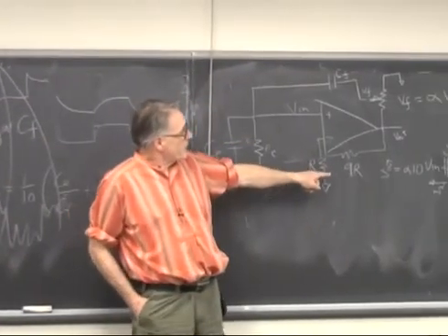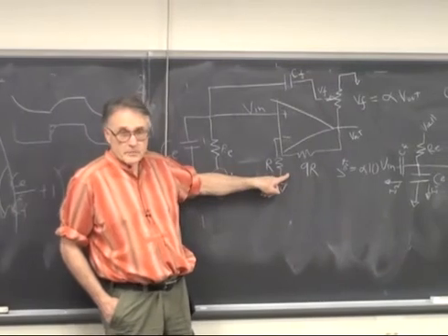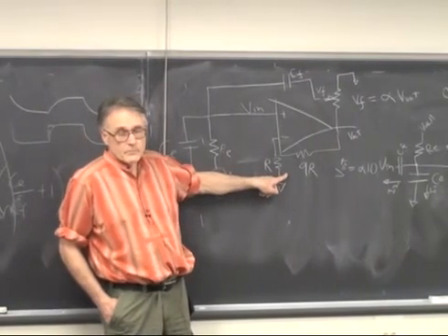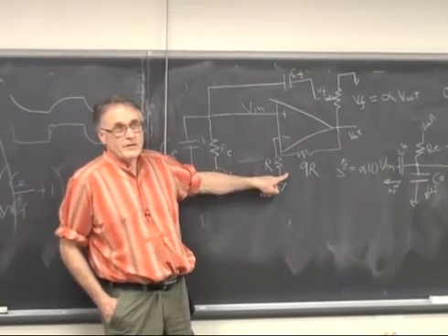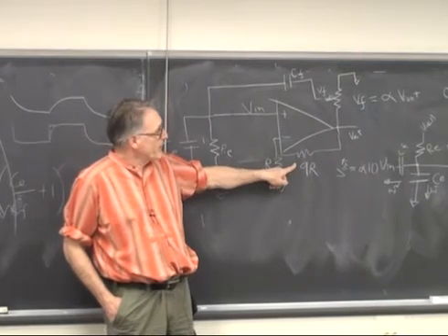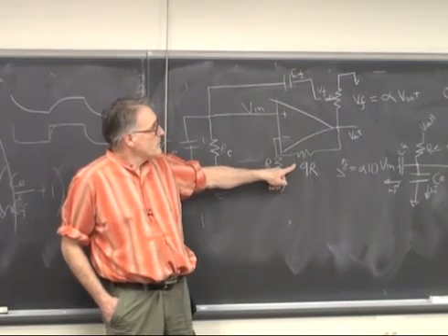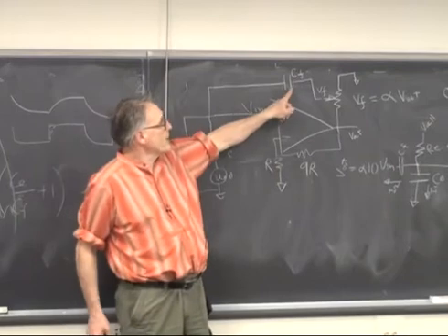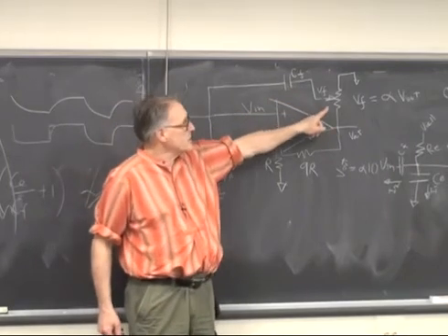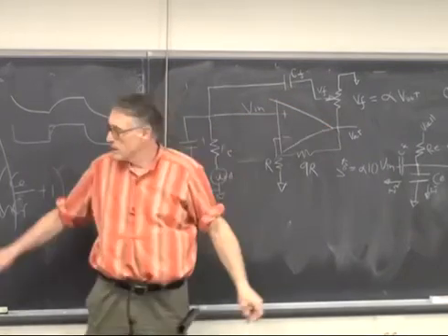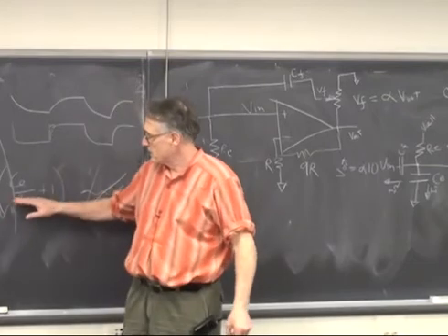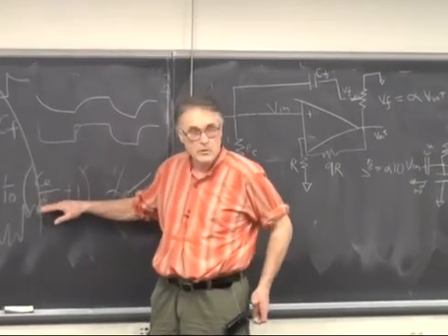So if I were to turn this up to 100 times, so we have a gain of 100 here, what does it mean for the circuit? It means that we have to drop the value of CF if we're going to have adjustability, because otherwise this ratio will be very close to 0.